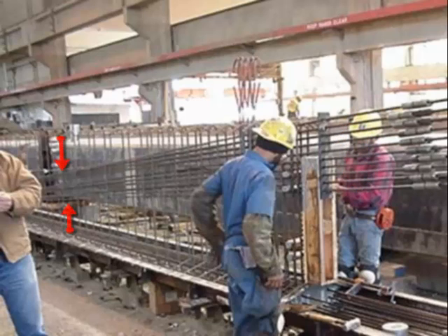Second, look at how the strands bundle together as they approach the hold down location. At WashDOT, strands are gathered or bundled together into a single location at the hold downs. And like the strands at the ends, this bundle can be moved up and down continuously. PGSuper uses this continuous vertical adjustment concept to locate harp strands in a girder.